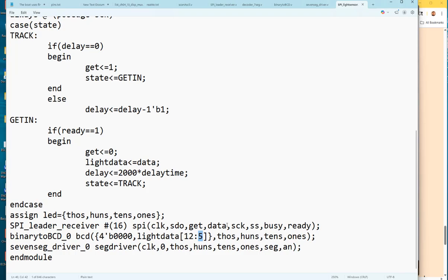So it's question number 3 in class number 11. It asks you the LSB of the ADC digitized output starts at which bit of the output. It actually should be bit 4, right? Should be bit 4. It's the 5th bit from the right, but should be bit 4. So for this code here,